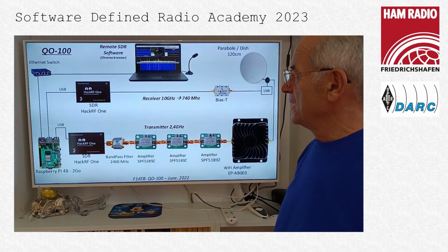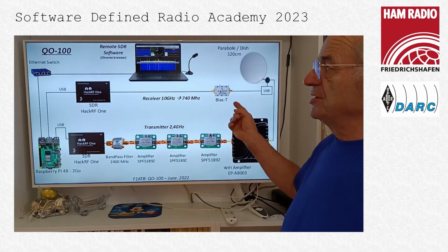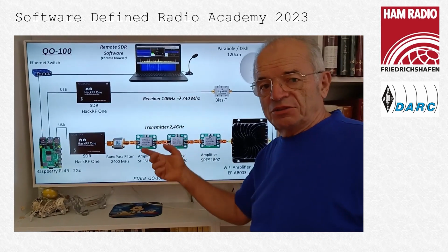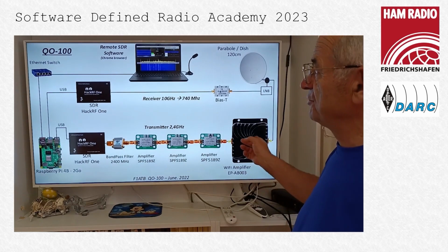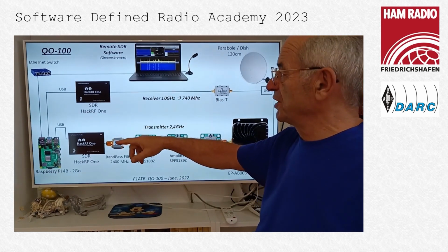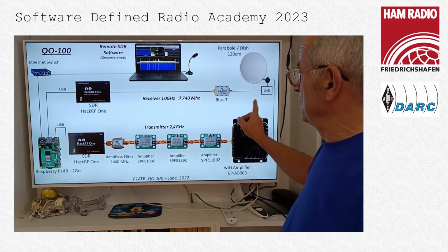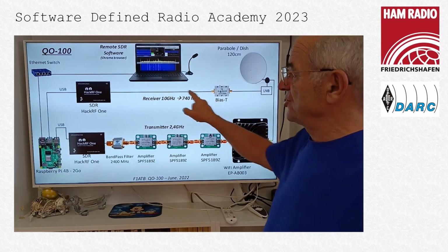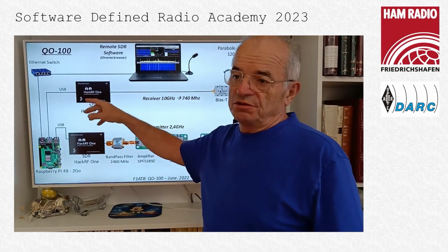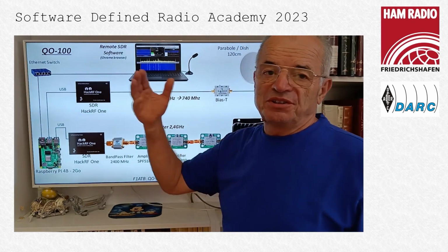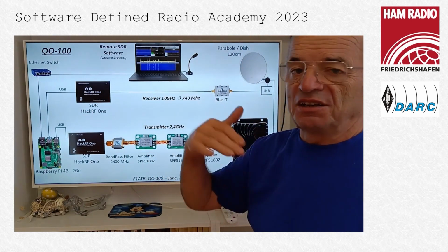Here an example of remote SDR for QSL. I have others at home, for example, the 2 meter band or the 70 centimeter band. This one for Q100 was my first one. Here the receiver side, so the satellite dish, the receiver uses HackRF. 8 bits is sufficient on Q100 because there is not an important dynamic between low signal and high signal.